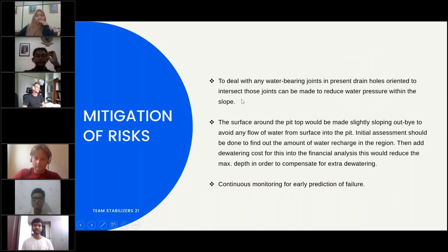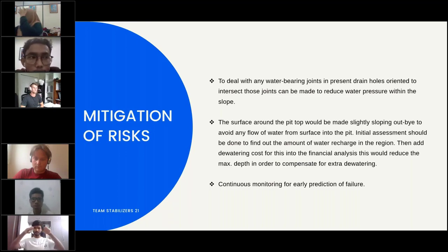To deal with water-bearing joints, we need to intersect the joint and drain out the water from time to time. In case of recharge, to reduce the water filled in the pit bottom, we can make the top of the pit slope a bit outward, so that whatever water falls at the top goes outward and does not fall into the pit and accumulate, increasing the dewatering costs.